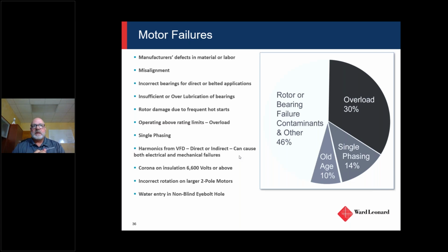What it is, is voltage that is on top of the coil, so you can contain some of it, but you're going to get some escape just because of the nature of high voltage energy inside of a conductor. It will escape, and eventually it just eats and etches through the insulation and will work its way to ground, and you have a failure.